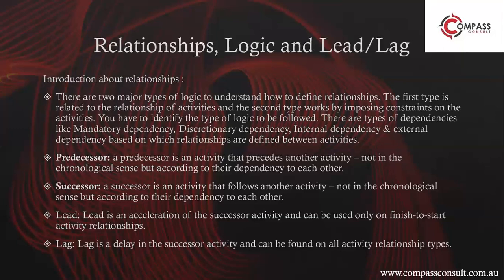Let's talk about predecessors. So what's a predecessor? A predecessor is an activity that precedes another activity. For example, let's take concreting. Before concreting, you'd be doing formwork and reinforcement, and formwork and reinforcement would be the predecessors for concreting. Similarly, a successor is an activity that follows another activity. So removal of formwork is going to be a successor of concreting, or curing of concrete is going to be the successor of concreting. It's very simple to understand.